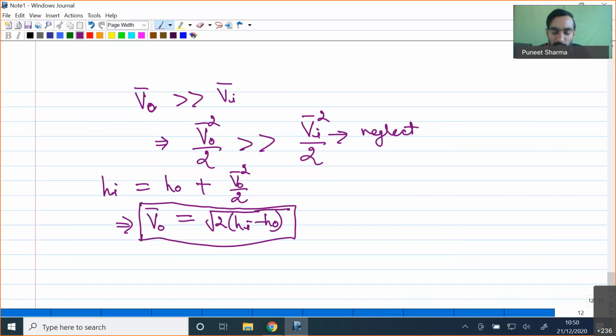Nozzles are employed in many applications. For example, we have nozzles in our diesel engine as a diesel fuel injector, where we have high pressure at the inlet of the nozzle and high velocity at the outlet in order to have good atomization of the diesel fuel. Apart from that, in our rocket or gas turbine engines, if we have to create propulsion, we want very high velocity at the exit of the engine. That's why we have a nozzle there also, where we expand high pressure gases after the combustion chamber, and that creates extremely high velocities.